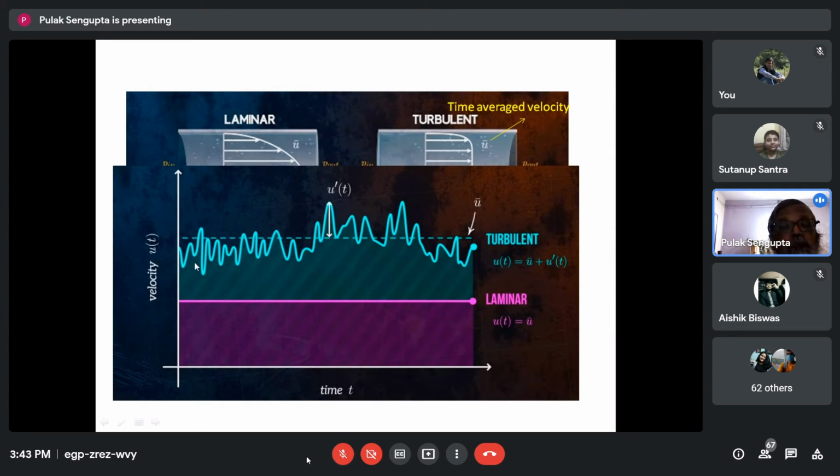But for turbulent flow, you have a time integrated average velocity, but at a particular time, if you want to get the velocity, you see these bumps. And that's why some spots move faster than others. And you have these gyratory motions, all possible chaotic movement of the water molecules. And depending on how far off the velocity is from the laminar flow, that guides what will be the amplitude of that. It's just like an electrocardiogram, and this amplitude will depend on how far off from the laminar flow; the more chaos in the system, the more these peaks will be.